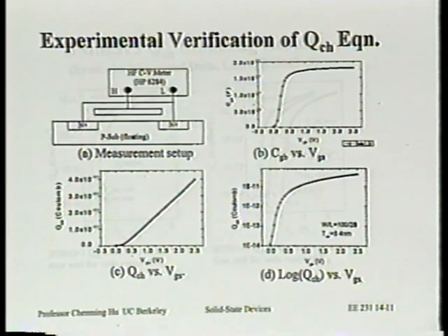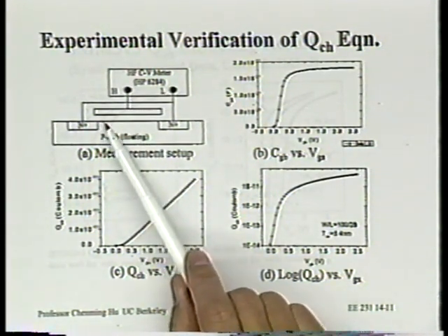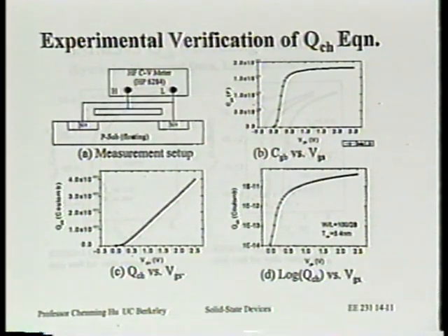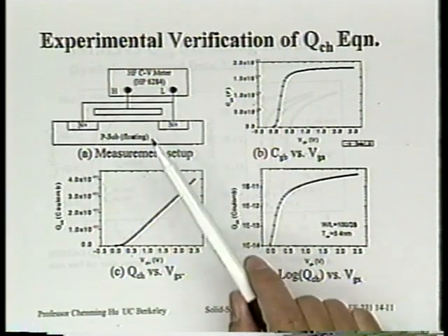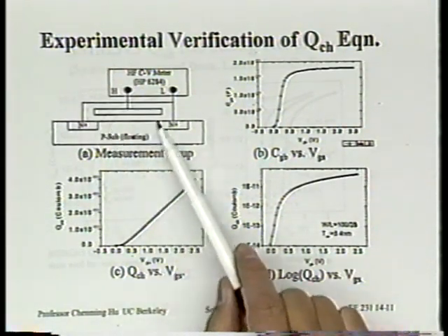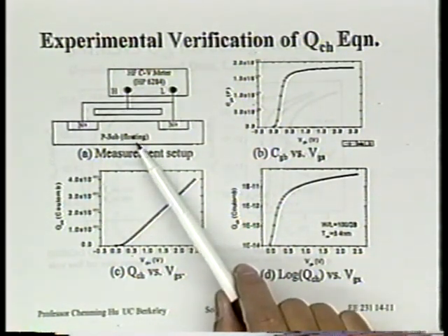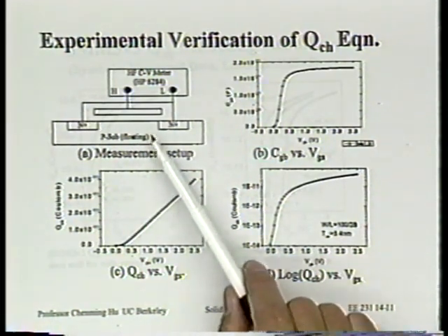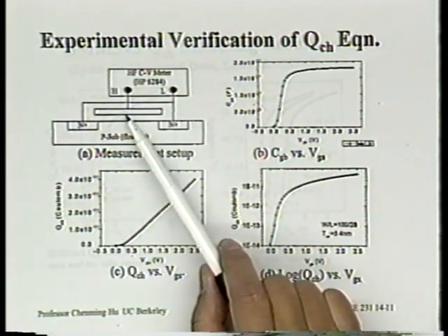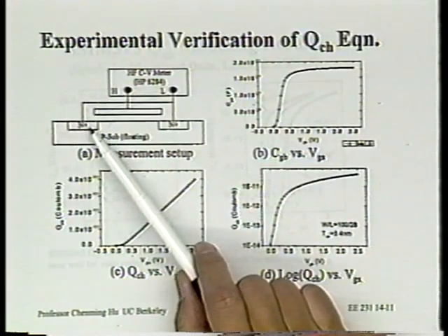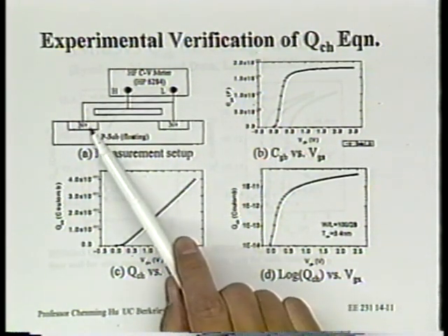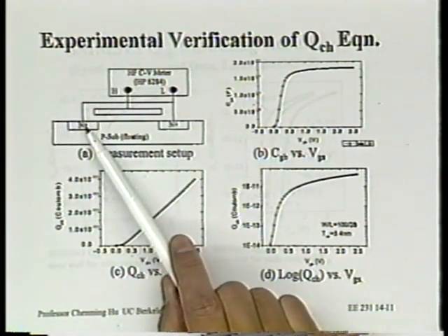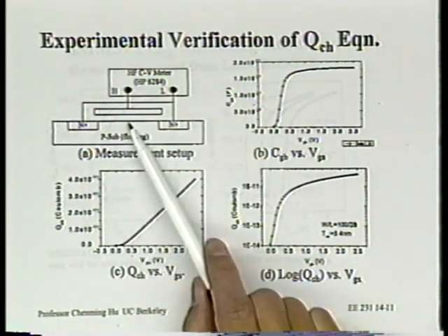You remember we talked about how you can measure the capacitance between the channel and the gate. Not the overlap thing. We just look at the channel charge, not the body charge, for example. By looking at the capacitor current flowing between the gate and the source with the source and drain shorted. The channel charge is supplied by the source, therefore, if you measure the current flowing into the source, you're actually getting the channel charge.